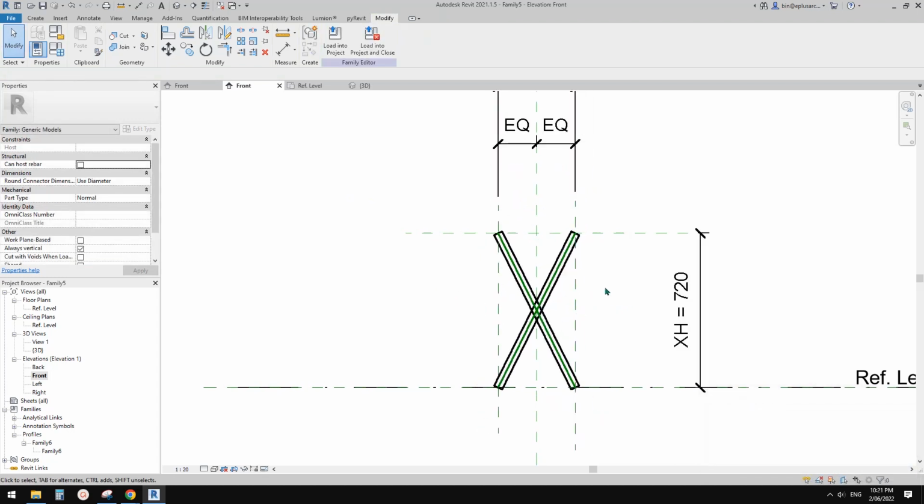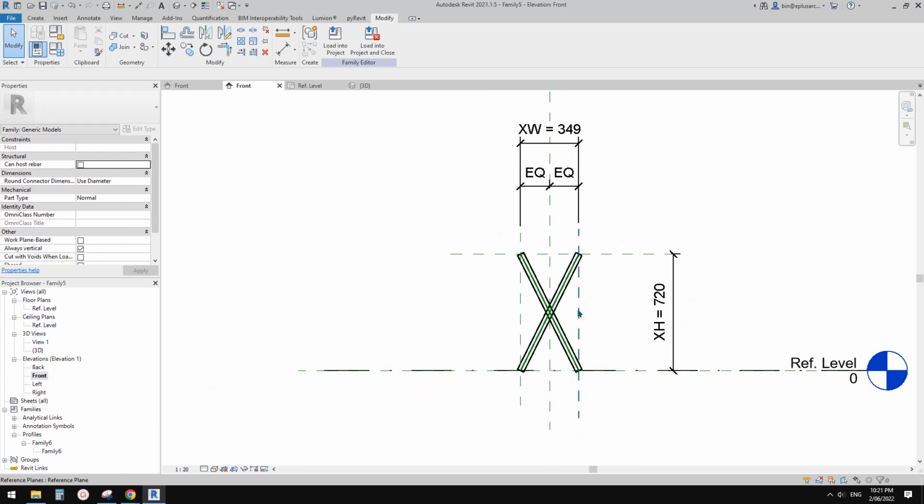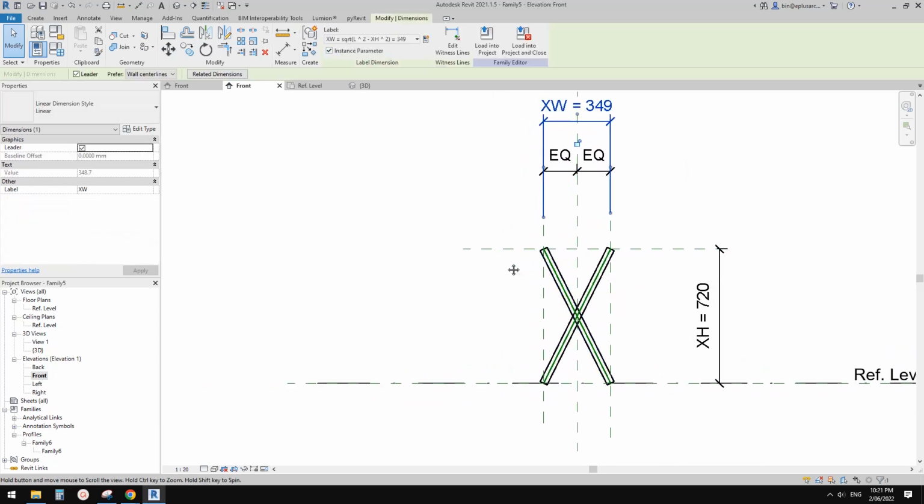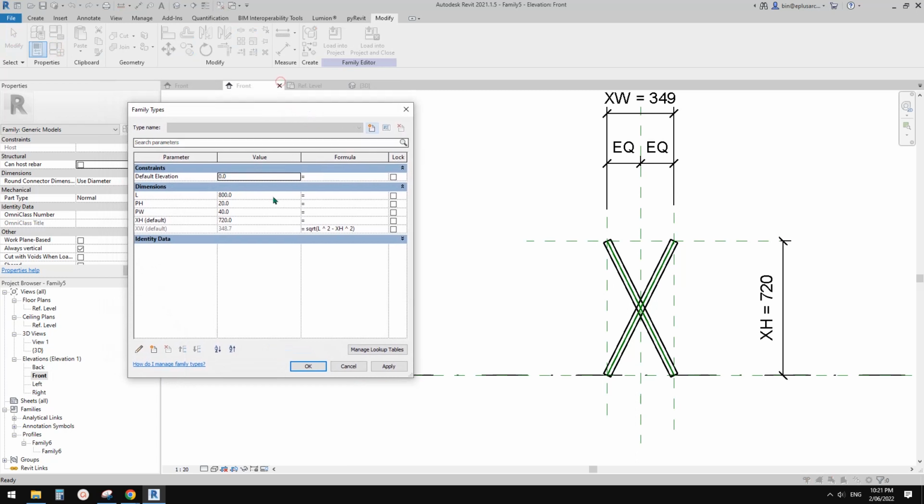Oops, sorry. Seems I can't do this, but this is instance. Yeah, that's fine. So we can check it in here. So if I change the width of this, oh, hang on. I think we're going to control the width. So instead of having the formula here, we need to put the formula here, and then we can control the width. So that's fine. Let's Control X, Control V, just swap H with W. Okay. Apply, all good. And then we can control the width.